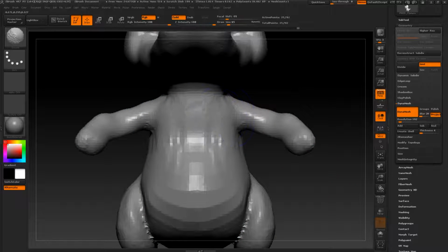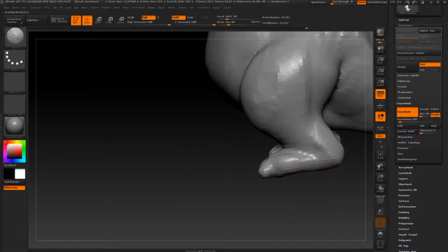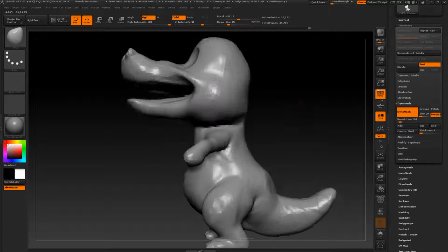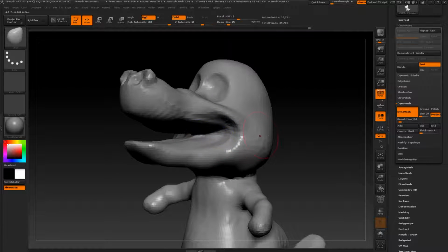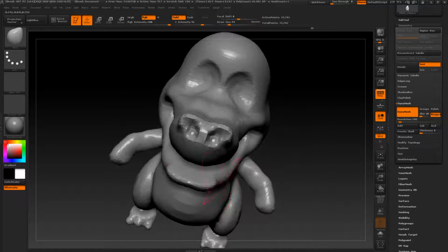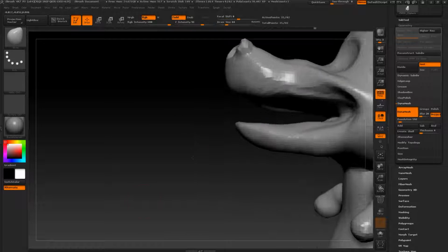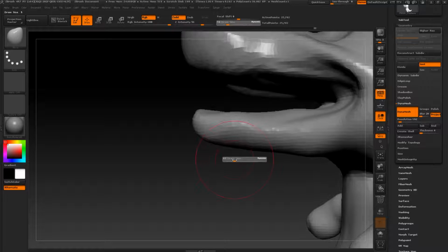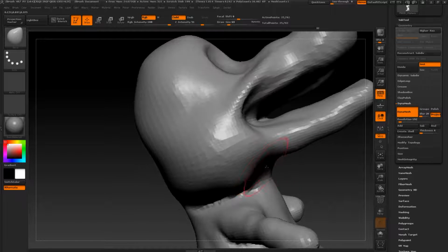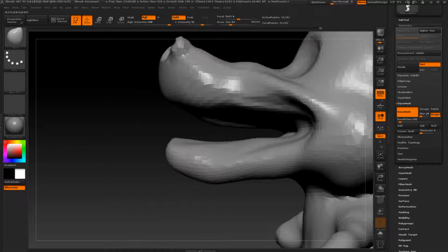It's not necessary to, let's say, add dynamesh. We could also go and make a direct ZRemesher now, so we have our new topology, because I actually won't stay too much in dynamesh. I like more the flow of ZBrush, a good topology that works with you with the flow, so it helps you.